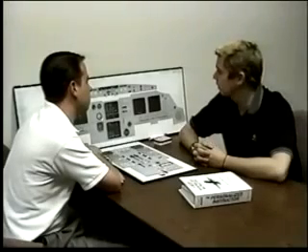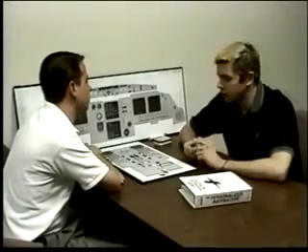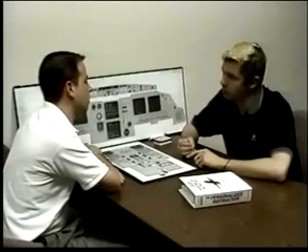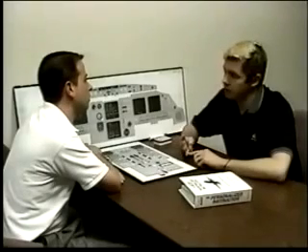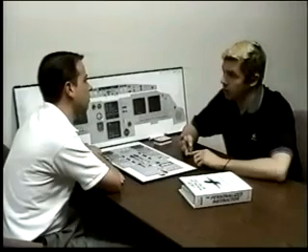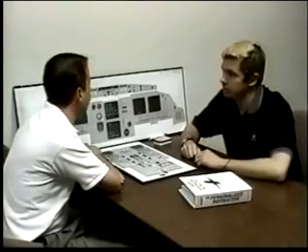The takeoff inhibit, we've got a list of items that are included on the takeoff inhibit. Those are basically things that are not inhibited, like engine fire, engine failure, or imminent engine failure with a loss of oil pressure. If I have a rudder or an elevator problem, a left and right elevator problem, a dual FWC fault, or if I have an APU fire.